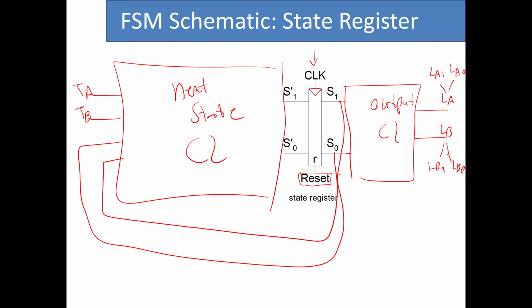But nonetheless, this is basically the same basic design that we had for the Moore FSM. So it was something like this. We had some inputs, some outputs, a next state, output, and then we had this clock that was connected to the register. So going from this basic design, or going from the equations that we came up with, to this is pretty straightforward.